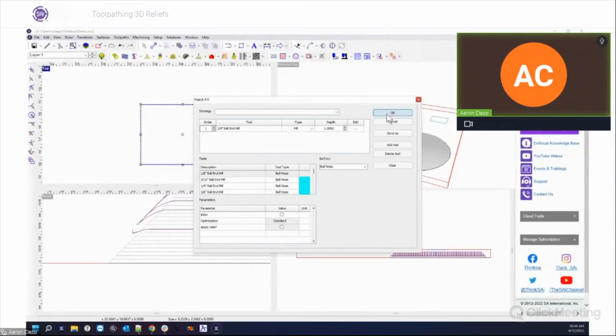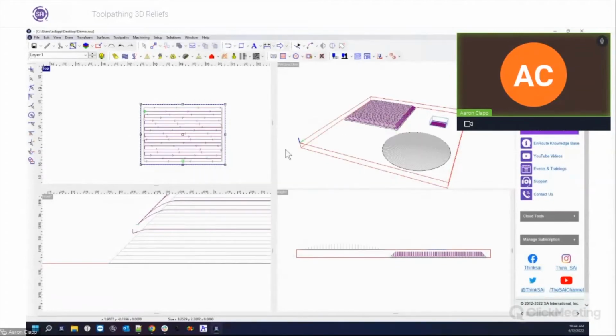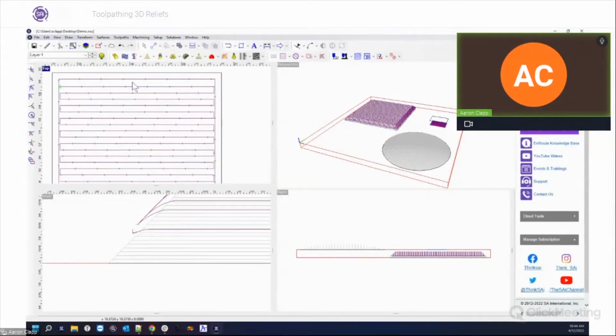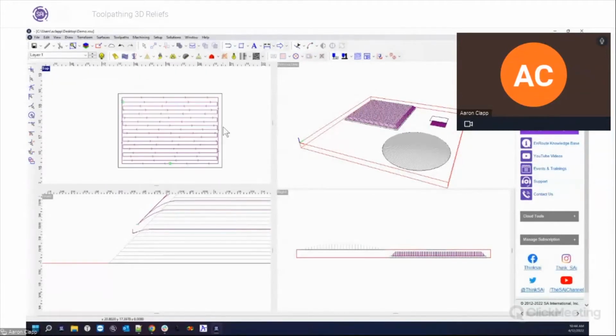It's just a square that I'm cutting with. We all know that it automatically offsets 1/2 the diameter of the bit so that the cut is actually the correct size. Because if it cut down the middle of your line, we all know that it would be too big or too small, depending on how the tool cut, or whether you're cutting on the inside or the outside, right? So that's fairly logical.